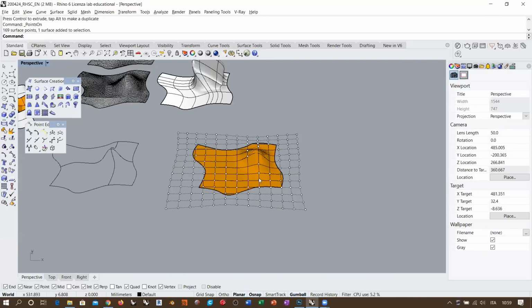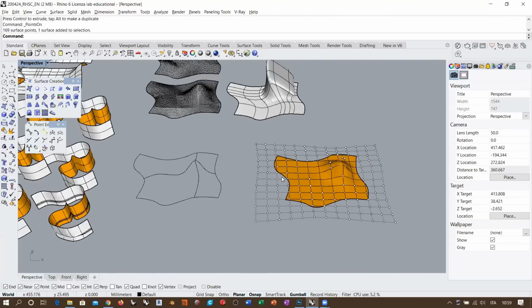So as I was saying, we already saw the analogy between the patch and the surface from planar curves. You can think about the patch as a surface from curves, not being planar. So the patch can create a rectangular topology using whatever type of input you want, because it is only taking a rectangular, deformable plane with the desired amount of spans.